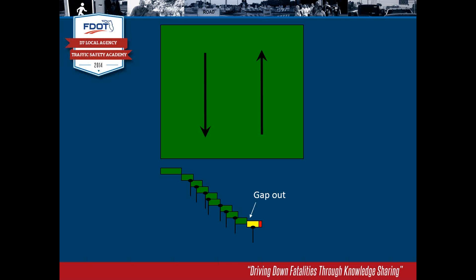So in this case, as shown here, it counted down 3, 2, 1, 0. It immediately shows the yellow, followed by the all red, and once it reaches the point where it goes to yellow, the controller is deciding who's going to get green next. That's where the controller makes the decision who's next.